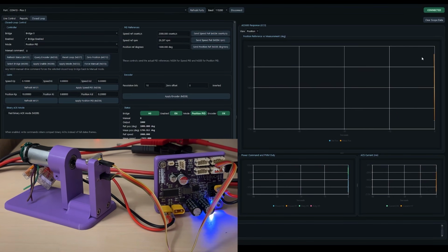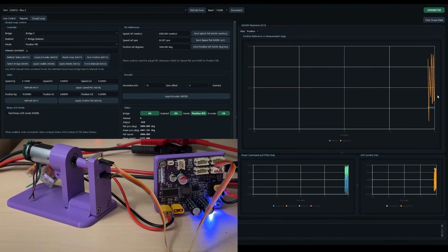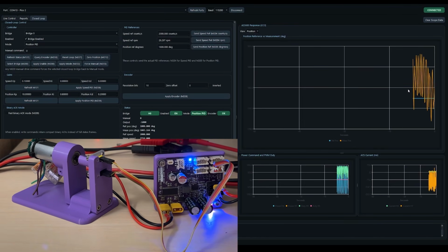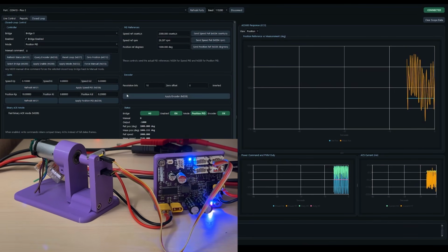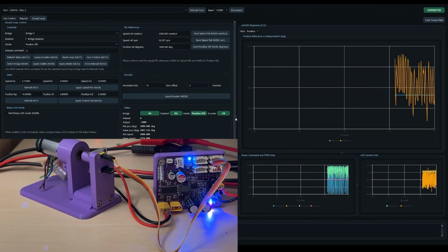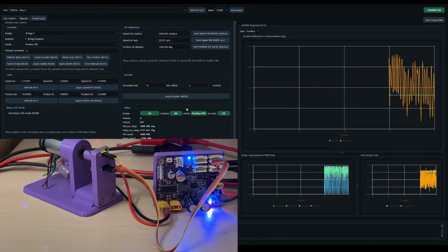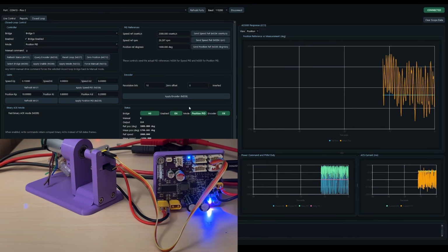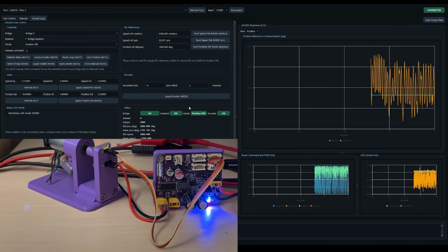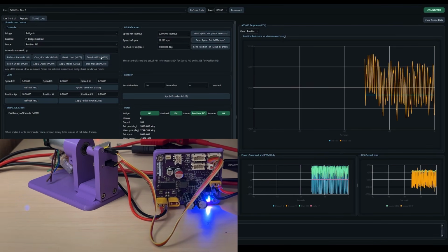Let's actually check that. You can see a bunch of oscillations here, and you can see that it's slowly starting to drop. That's because the accumulator of the integral part has filled up since it had to spin up a bunch. And then you can do some other special stuff like gain scheduling. You can rate limit the actual PID controller and other stuff.